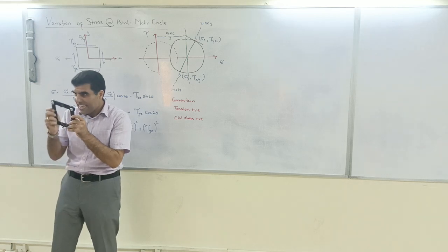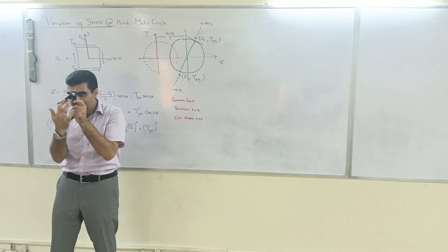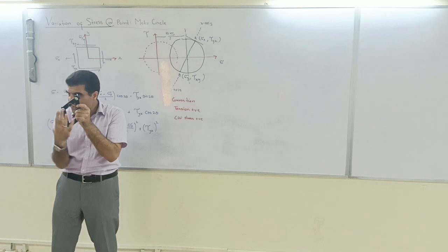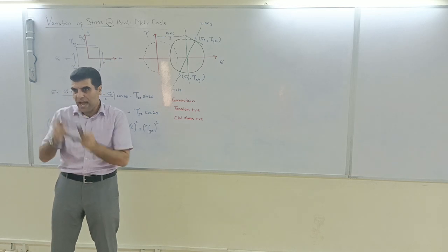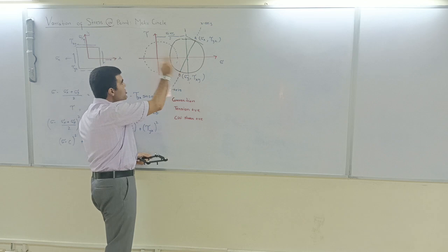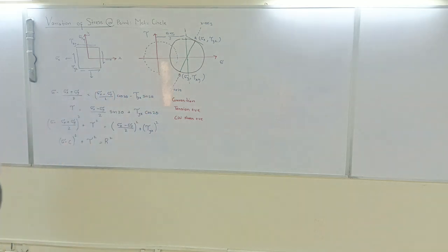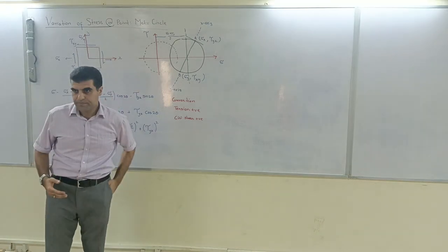And it is true that when you have a shear on one axis, the principal axis will have axial stress, one tension and one compression. Tension and compression, and that's what you can see over here. So my point is that if you understand the Mohr circle, you can interpret lots of things using it.